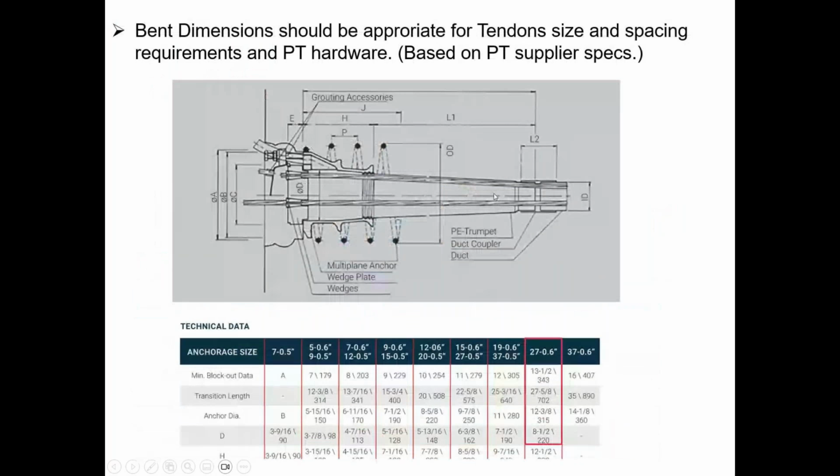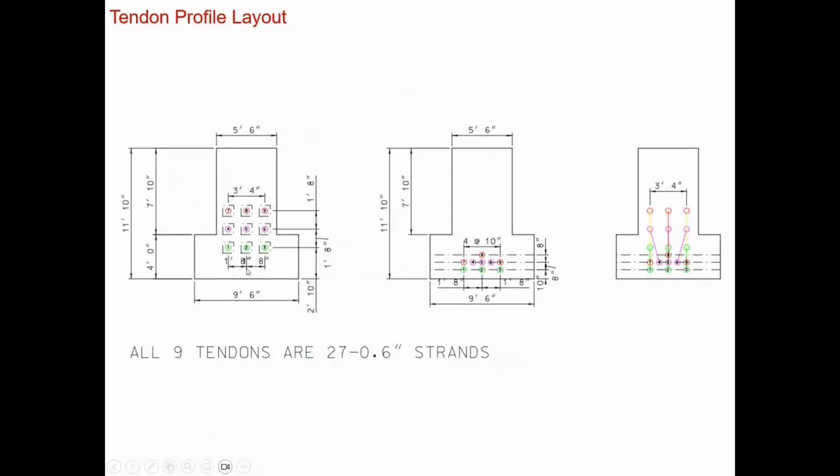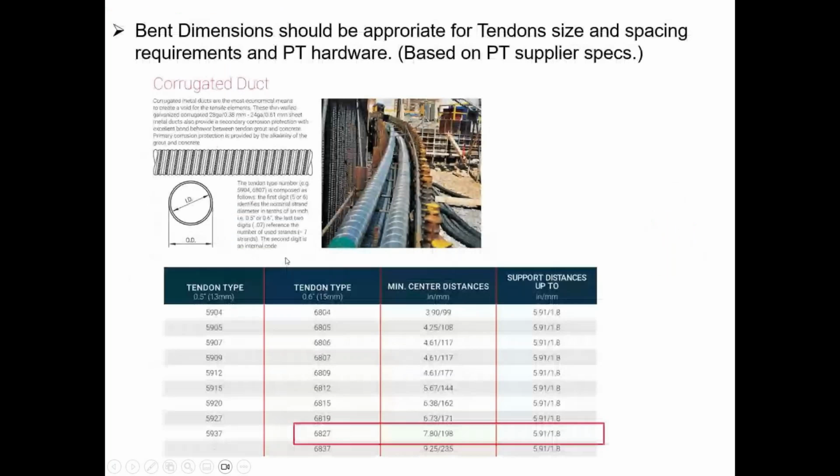Also, it's very important to review the anchorage zone area, like what the actual dimensions of the anchorages are, the inner and outer diameters, and basically make sure that whenever you get to the end block, whatever spacing you decide on from center to center of the anchor plates is sufficient to get the jacks to fit in and jack those tendons as well.